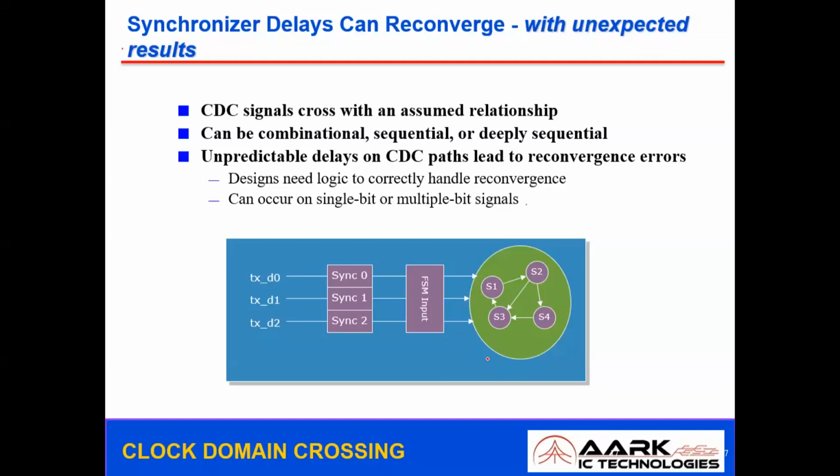These control FSMs will add additional hardware along with the synchronizers. It will be an overhead on the design because it is not contributing anything to the logic. So from a consumer perspective, this is additional logic that is added, an additional cost. But we are able to predict the behaviors. So we are changing from an unpredictable nature to predictable behaviors. That is the beauty of this reconvergence.